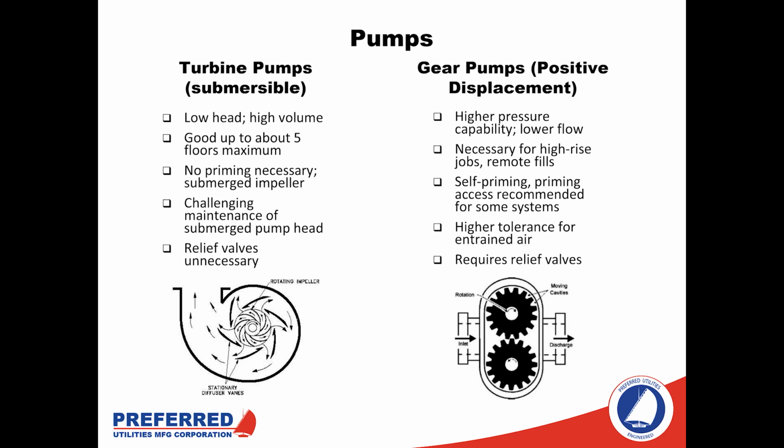The separate relief valve offers an advantage because if we were to deadhead this pump, it is still going to flow fuel through the pump, through the discharge, to the relief valve, and then the relief valve would divert that fuel back to the main tank at low pressure. With an internal relief valve that's installed in the pump head itself, it merely circulates a very small amount of oil from the discharge right back to the inlet. And this small amount of fuel is not going to be useful long term to continue to lubricate the internals as well as maintain a proper operating temperature. So in this case, an internal relief valve may not be appropriate for the transfer pumps, but you will see it on things like the polishing skid or return pumps at the day tank that aren't necessarily as critical for providing fuel to the generators themselves.